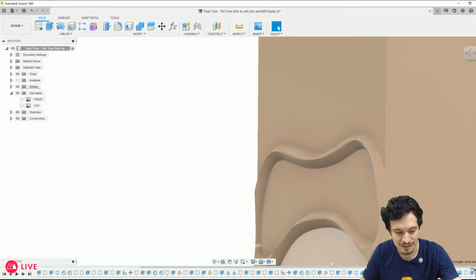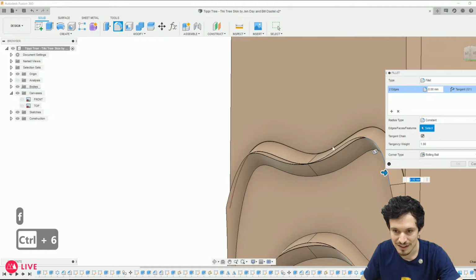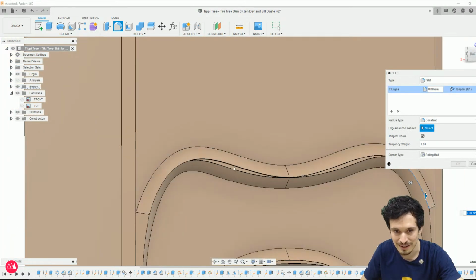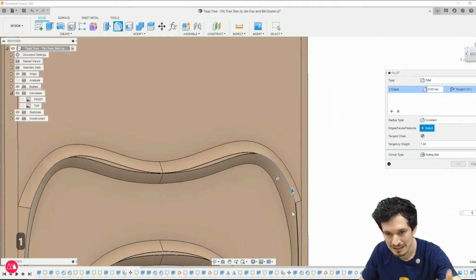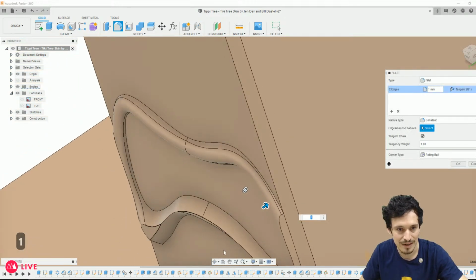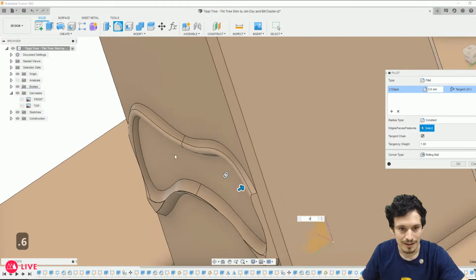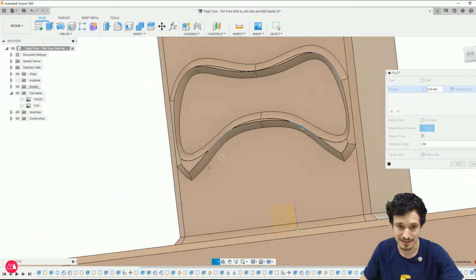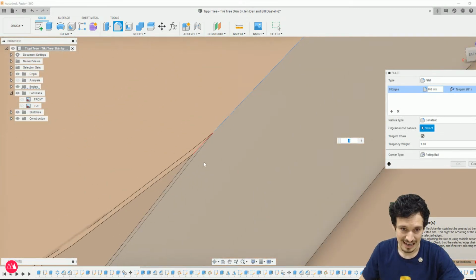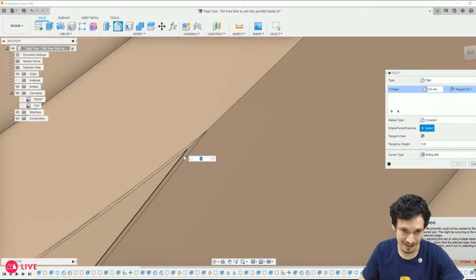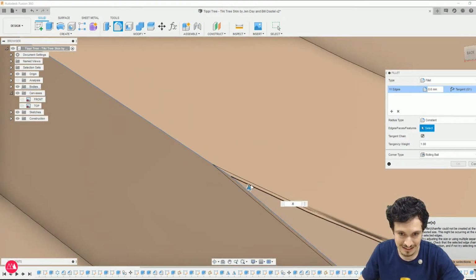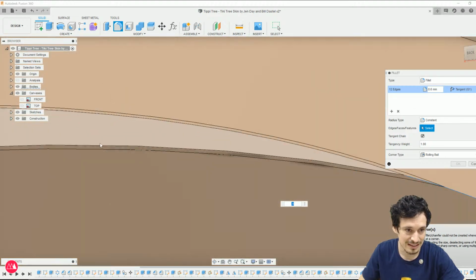It would be nice to have maybe a fillet on the end here, even though it is a weird surface because it's not a uniform thickness, so there are some areas that don't come to a point. Let's see what happens if I try to throw a fillet on there. Hey, not bad. Fusion 360, in my world, is a lot of just like, let's see what happens. Yeah, so here there's a weird thing going on where it splits. We can try that. Try selecting the split and see if it allows us to do the fillet, but I have a feeling it won't.